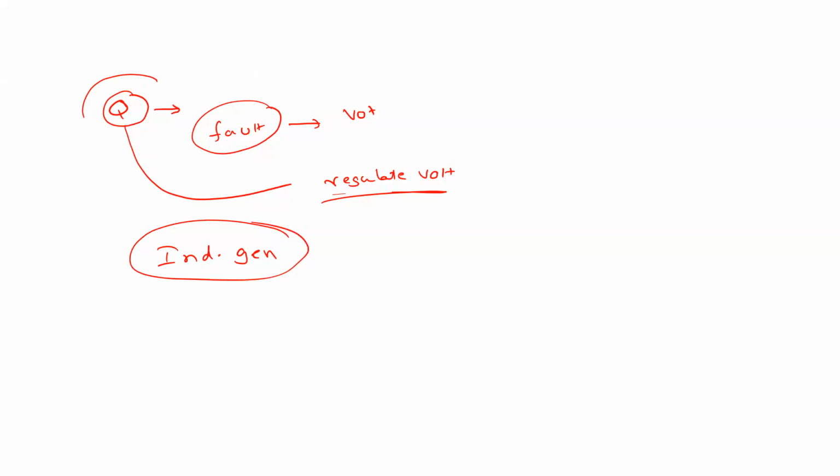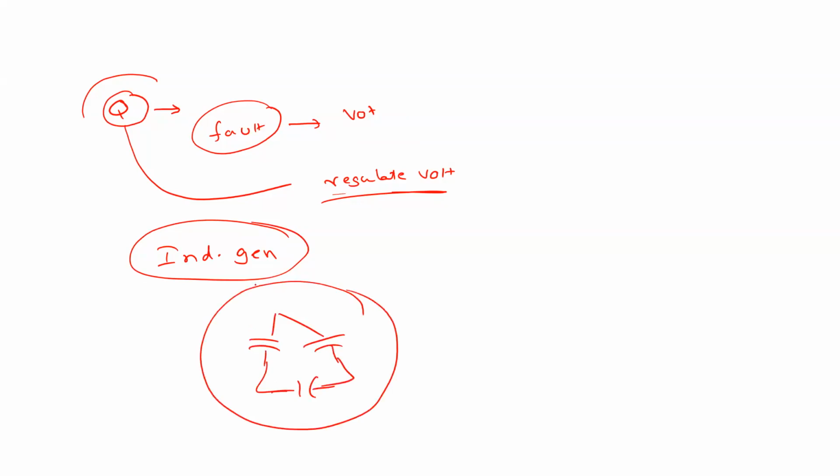If it is wind energy, you're aware that for wind energy you require a lot of reactive power, right? So that's why we normally connect capacitor banks across the induction generator. In earlier days we normally used these capacitor banks, but they require a lot of maintenance, and moreover the control of the reactive power is not accurate.